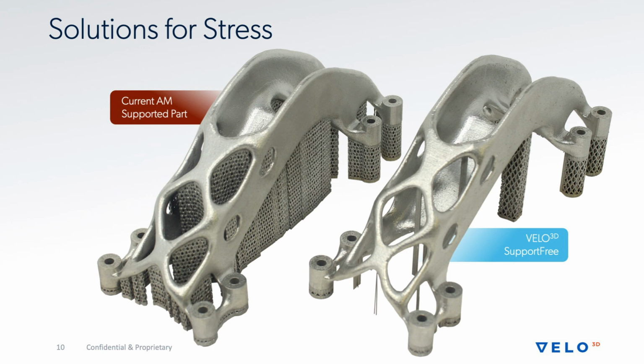The one here on the left is set up so that every surface below 45 degrees from horizontal, down facing, is supported. And the object on the right is the same exact geometry, but printed with the design guidelines that I'm going to go through in the next slides. And you can see there's a dramatic reduction in these support structures. So you can get away with printing this geometry, but at the expense of these support structures.